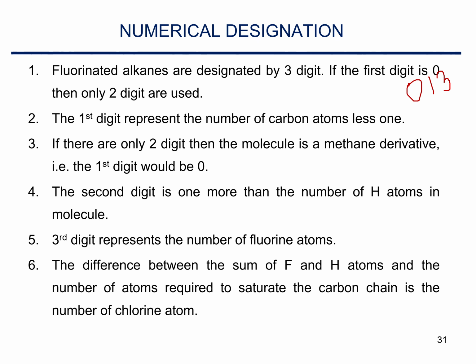So how will you calculate this? Your way of calculation would be like this, just keep in mind C H F. These three values suggest C, H, F. The first means C, the middle one means H, and the last one means F. So how? Just plus 1 to this and minus 1 from this. That means if I tell you freon 13, what would be the name of freon 13? Actually, it would be C plus 1. That means 0 plus 1 is equal to C1.